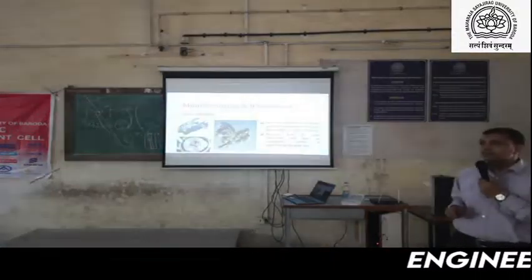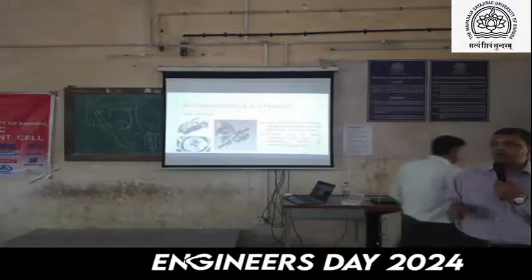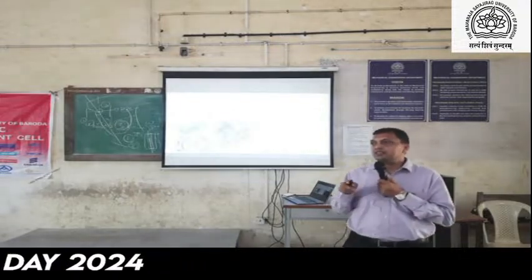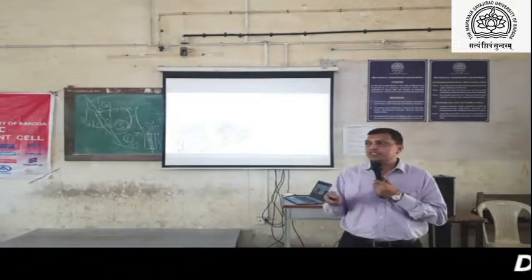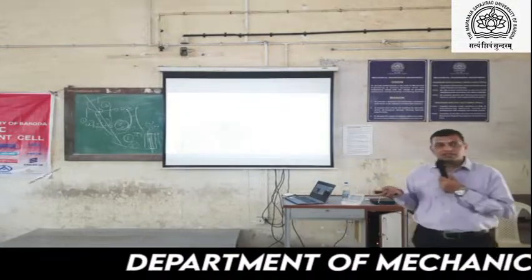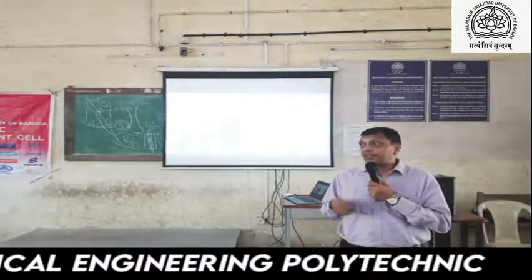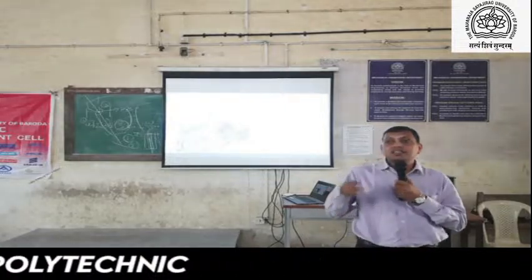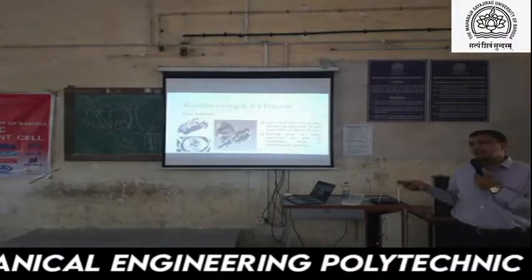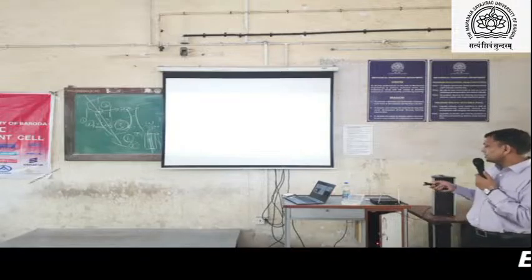Gear assembly is whatever the design releases in the bill of material. Now what is the bill of material? The bill of material is the bunch of components that are decided to be manufactured or assembled. In that case there would be the pinion, gear, shaft, bearing, oil seal, covers, gear case, fasteners. These components are included in the bill of material, and they form one assembly unit that will be assembled.